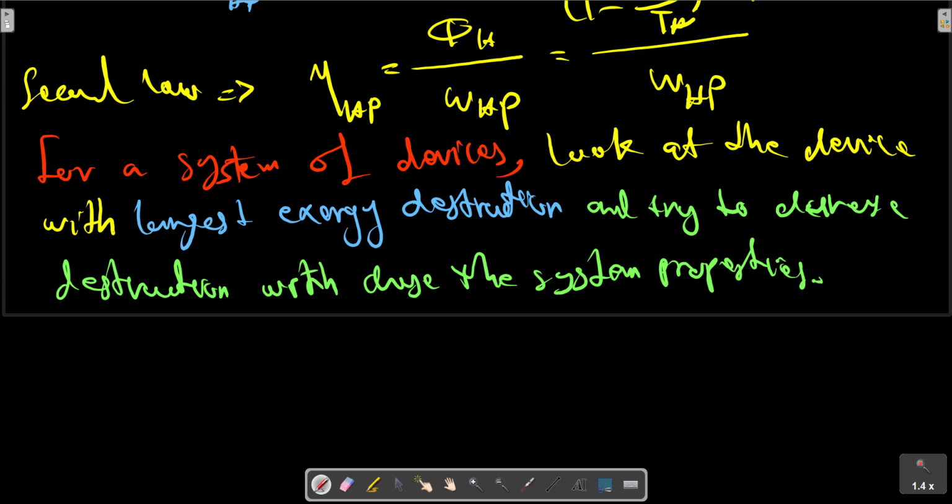For the power plant, for instance, try to lower the temperature difference in the heat exchanger, reduce the pressure and heat loss in the piping, and ensure that the turbine is operating in its optimal range. To mention just a few of the more important places that have exergy destruction: in the steam condenser, a large amount of energy is rejected to the surroundings, but very little exergy is destroyed or lost. So the consideration of energy is misleading. The flows and fluxes of exergy provide a much better impression of importance for the overall performance.